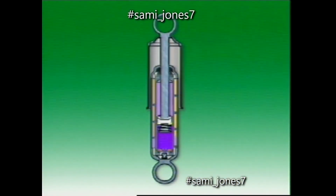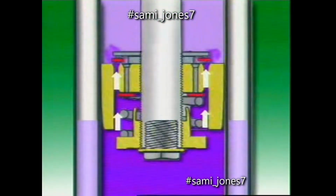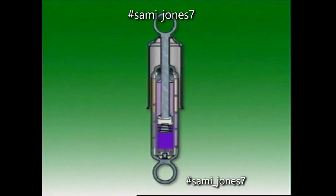The hydraulic shock absorber provides its dampening action by transferring oil under pressure through valves which restrict the oil flow. The twin tube type is the most common. The outer tube is normally attached to the suspension member at its base, and the inner tube provides a working cylinder for a piston which is attached to a piston rod.